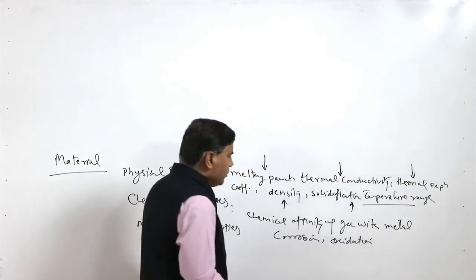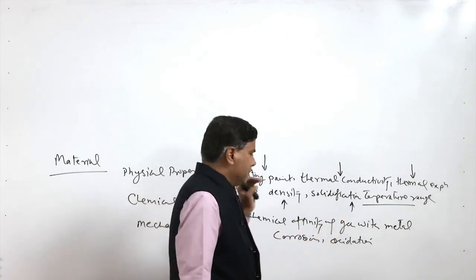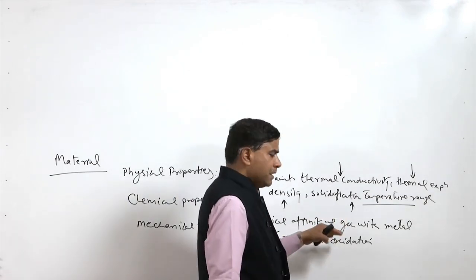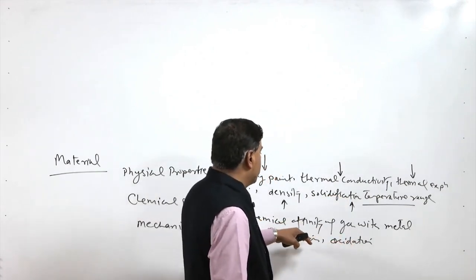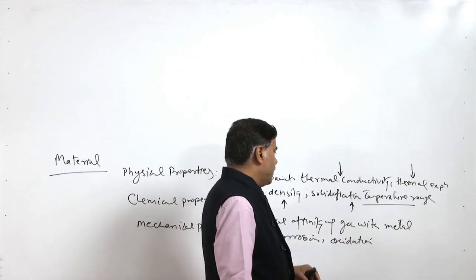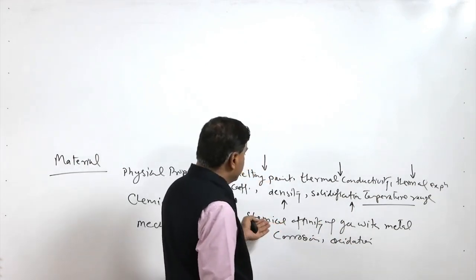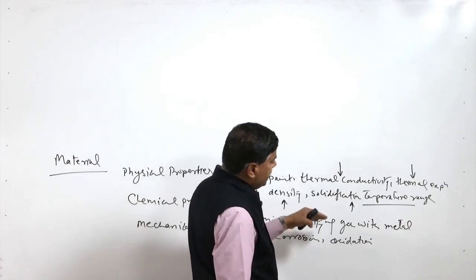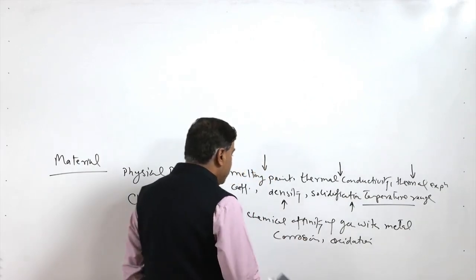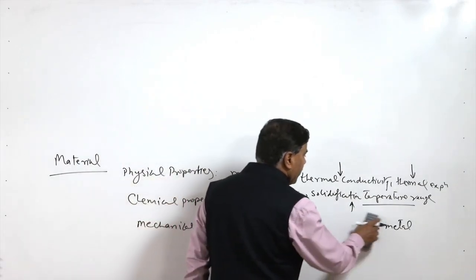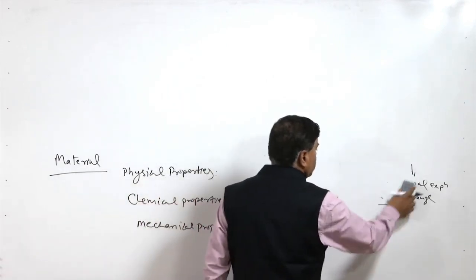Since during the processing, like welding and machining, as well as during forming processes at high temperature, there is a tendency of oxidation of the metal, and in the molten state during casting, the high affinity of the molten metal with the gases leads to an increased tendency for inclusions and gas porosity formation.